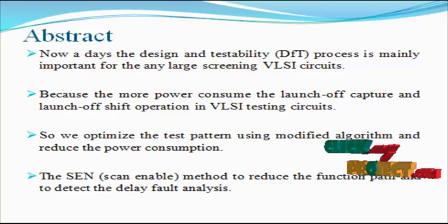Next, we will see the abstract for the product. At-speed and even faster-than-at-speed testing of VLSI circuits aims at high quality screening of the circuit by targeting performance related faults, on a compact test set with highly effective patterns, each detecting multiple delay faults, desired for low cost.